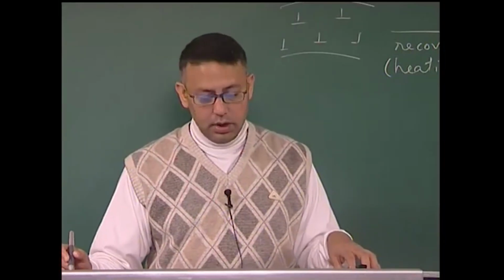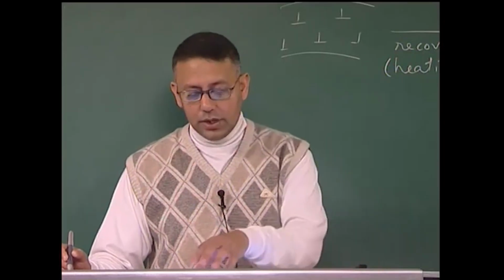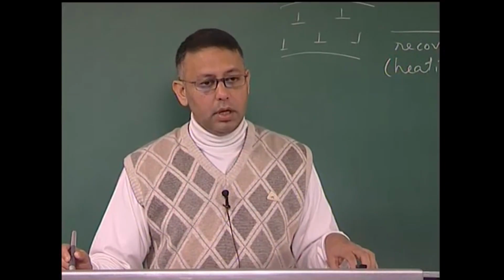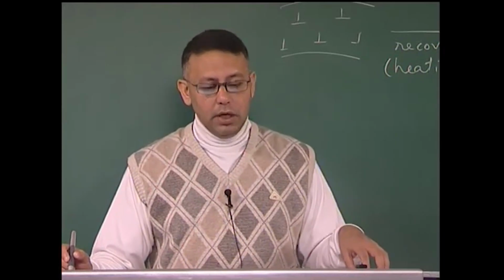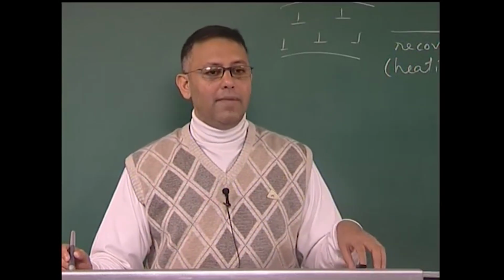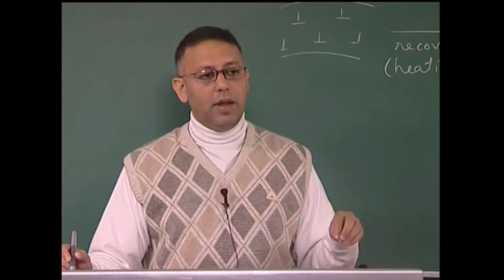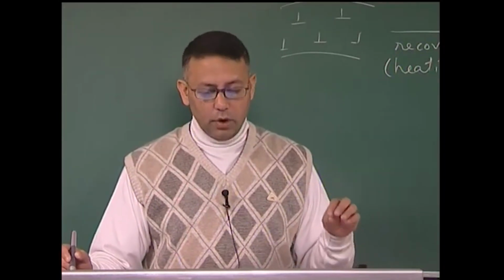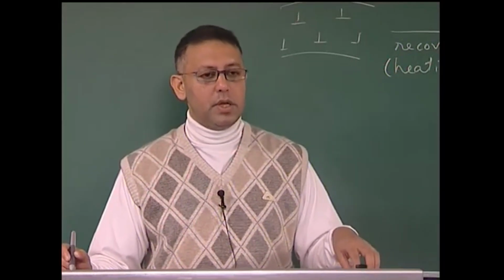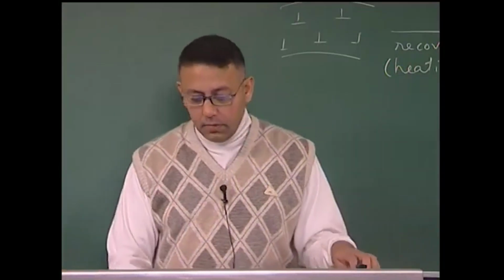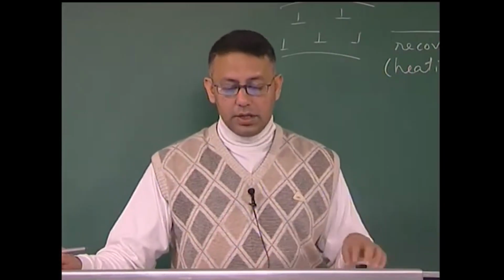Therefore, clearly from these two examples which we have considered now, one being the case of heteroepitaxial growth of islands, and more importantly heteroepitaxial growth of buried islands or the second layer, and the case of galvanic corrosion, residual stresses can play a very important role, and they need to be elevated to the level of phases and their distribution, or the level of defects and their distribution. Therefore, a comprehensive definition of microstructure should involve phases, defects and residual stresses, and of course, their distributions. And these two examples are very, very important in exemplifying this important aspect.